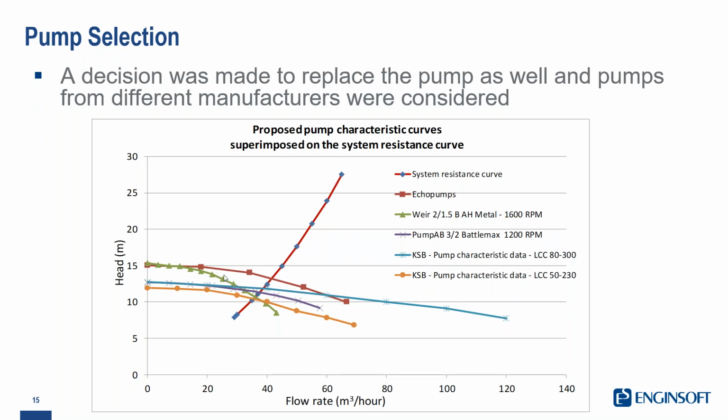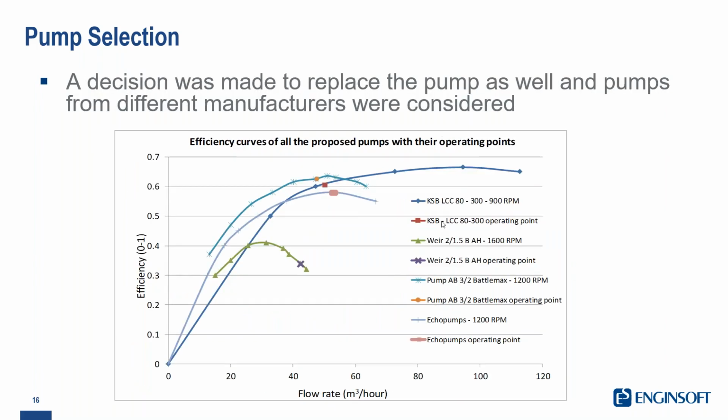so you can now select a better pump that is more reliable and can work in an efficient way according to this new system curve. For sure, you can also make some consideration about the efficiency curves and have an idea of energy consumption when selecting the new pump.